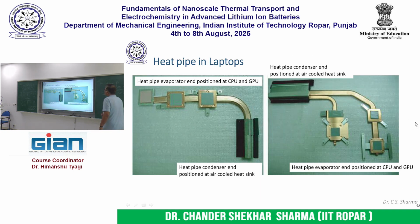Okay. So here is just a picture of realistic heat pipes, how they are being implemented in laptops. For example, here you have the two evaporator sections, and then this is connected to a condenser and then to the heat sink, because in the laptop, let's say your processor is somewhere here, right, but the fan is somewhere here. So the job of the heat pipe would be to carry the heat from here to the heat sink that is connected to the fan. Okay.